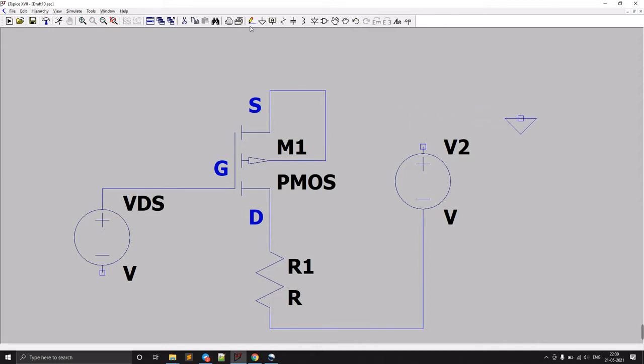Here we need to make one ground, and here also we need to make one ground, or else we can connect from this to this source, and the source is anyway connected to this positive and it is connected to the ground. So let's connect it. This is to be connected in order to complete this circuit, and this one to the ground, because here we need the negative supply. And this also, we can connect to the source, or we can just connect this to the ground, because these both are at the same potential. These two form the same node.